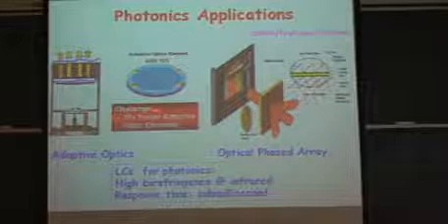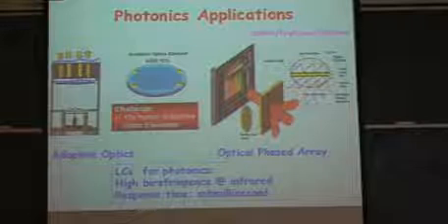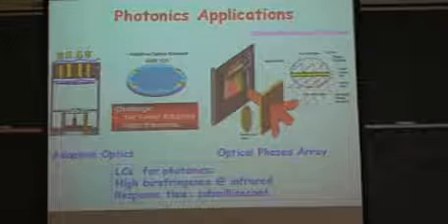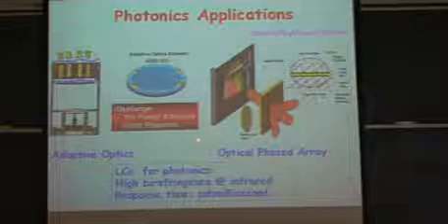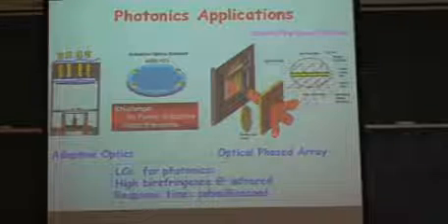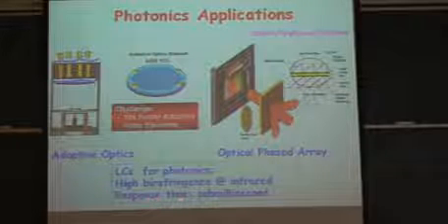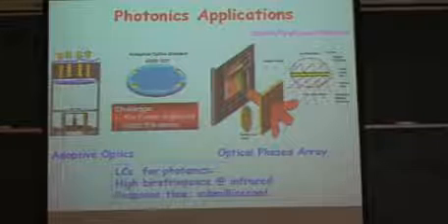Liquid crystal-based phased arrays require very little power, and are insensitive to acceleration, especially for large apertures, and their cost drops greatly with volume production. So with high birefringence liquid crystal material, we can realize sub-millisecond response time at infrared wavelengths.